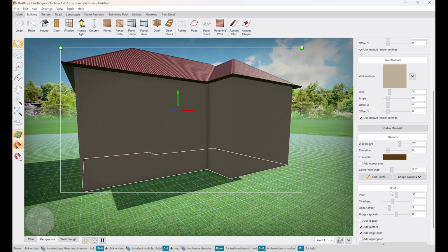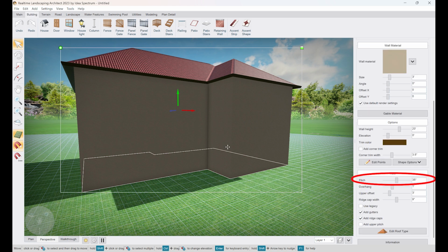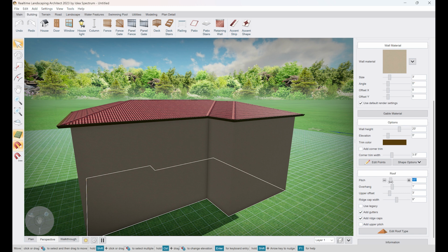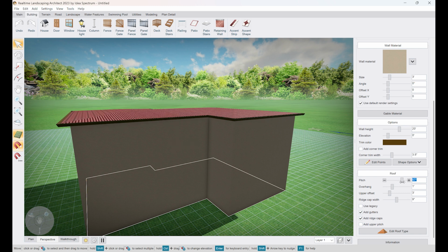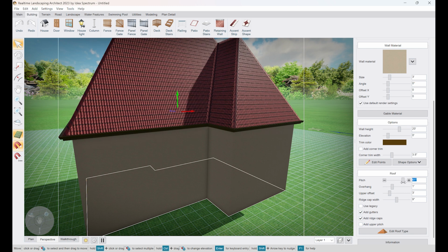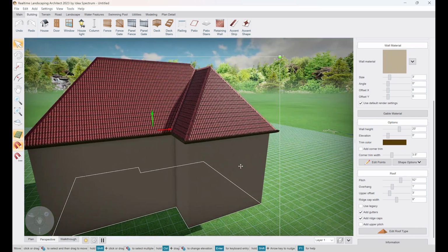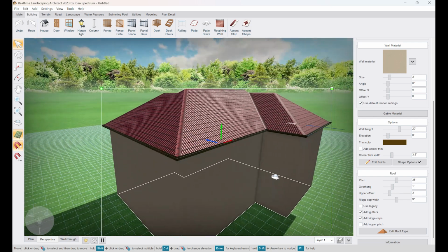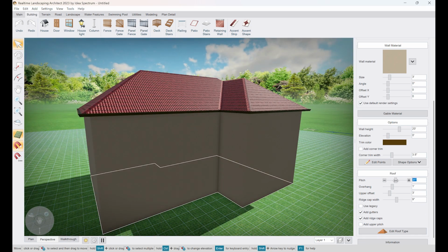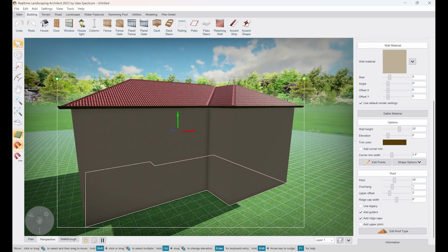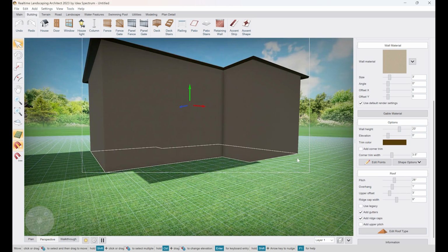The pitch on the roof here is the next thing. The pitch can be adjusted to bring the roof flatter. If it goes down, the roof goes flatter. And if the pitch goes up, these are degrees, so now it's really quite the castle-y roof right there. It defaults to 35 degrees, which I guess is standard in roof building. But a lot of times I'll find that I'll need to trim it down a little bit because they're not such sharp angles. The overhang defaults to a foot, which is the overhang from the wall to the roof.